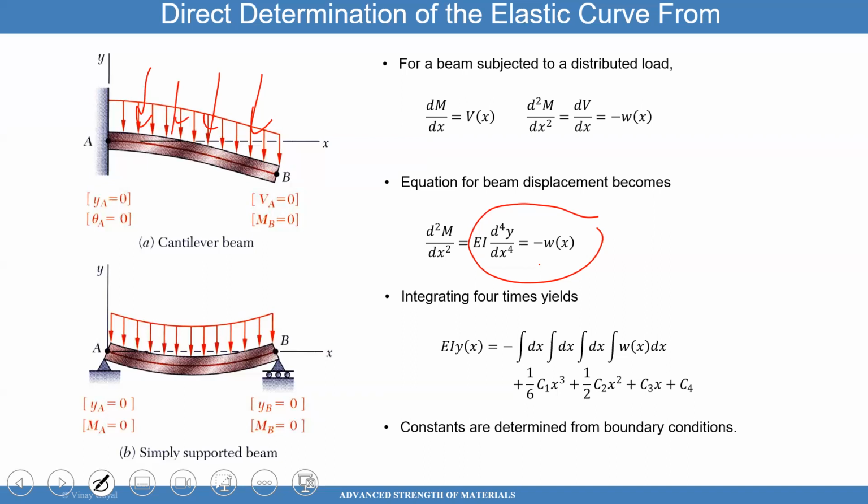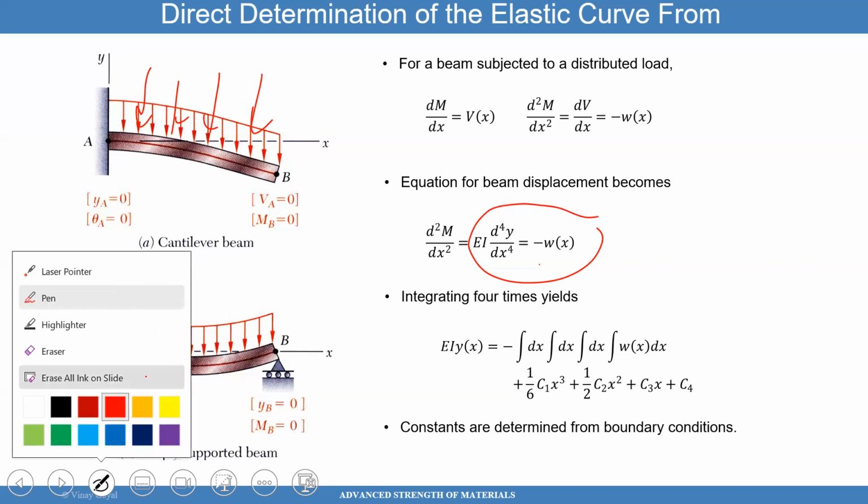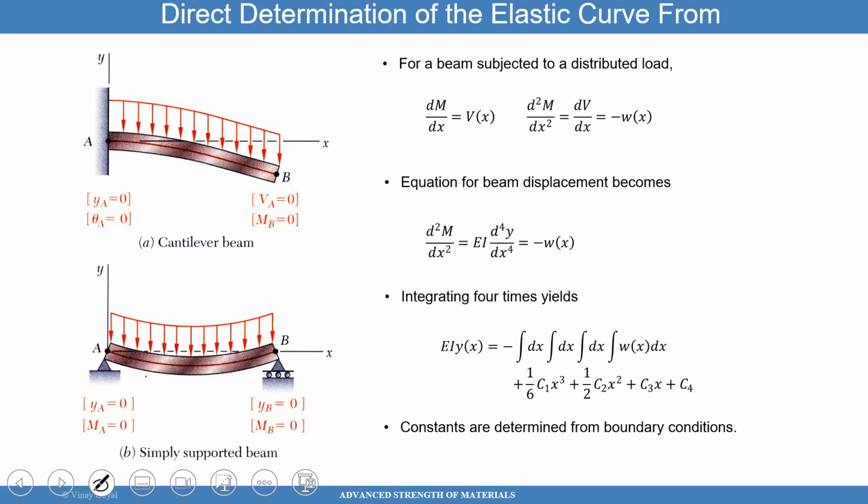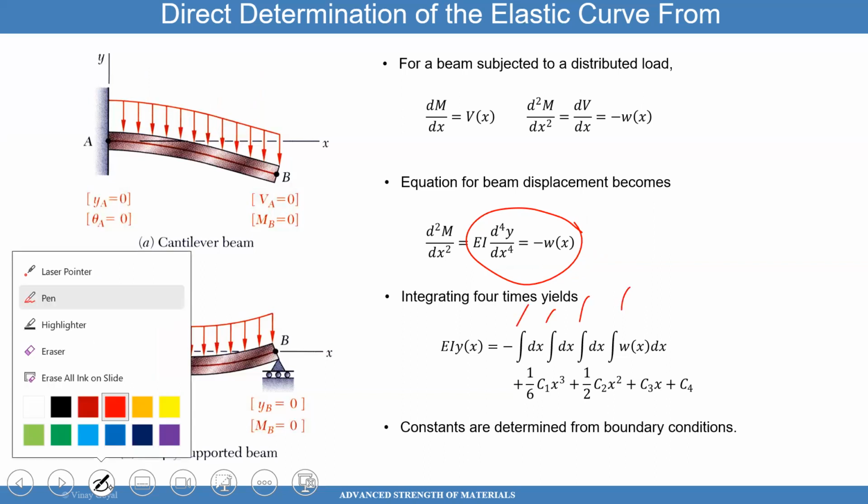The other way is to look at first principles, the way I did in today's class. If you did that, I think things will make sense to you. That's why the negative sign is there: in my previous derivation, w, the pressure load applied to the beam, was pointed upwards. So you'll start with this equation. If you have a distributed force like that, you'll integrate that equation 4 times: once, twice, 3, 4 times, okay?